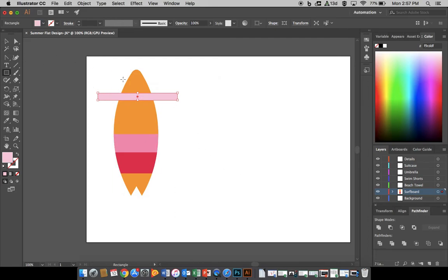So I want you to actually have two. So I'm going to hit V so that I end up with my selection tool. There are two ways that you can duplicate this. You can do copy and paste, and that is Command C, then Command V for paste, V as in Victor. But an easier way is to hold down, so when you're clicked on here, hold down Alt and then drag, and boom, I've got two of them. So I was clicking on this rectangle, pressed down Alt and held it, and then I dragged that other rectangle off, and that gave me two rectangles.